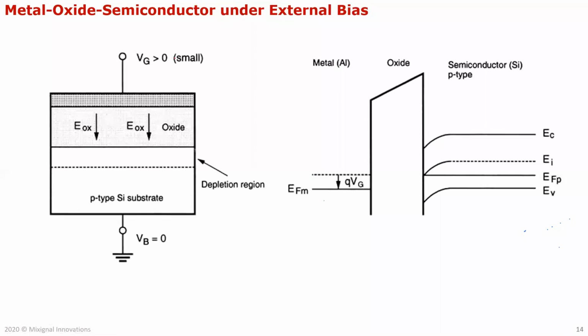Now what you do is you apply a little bias to it. I'm going to apply a positive bias. I won't talk about negative bias now, just positive bias for this thing. So you're applying this voltage VGB, gate versus bulk. Let's call this bulk, let's call this gate. I'm just naming them so that it kind of builds you up for the MOS terminologies as well.